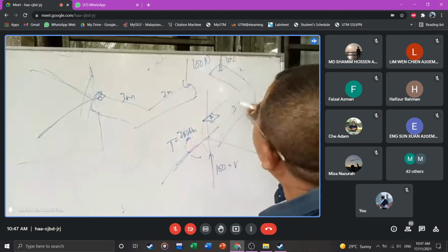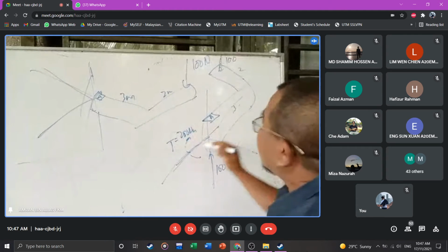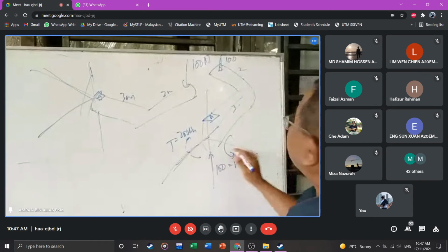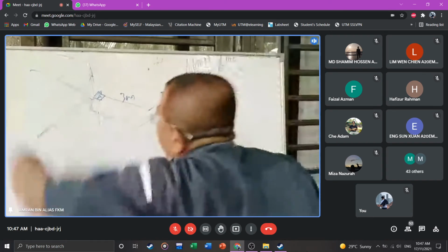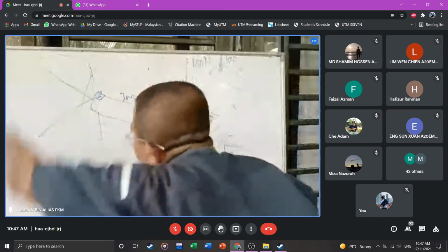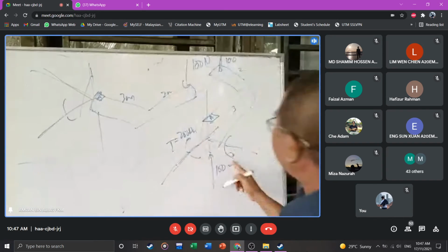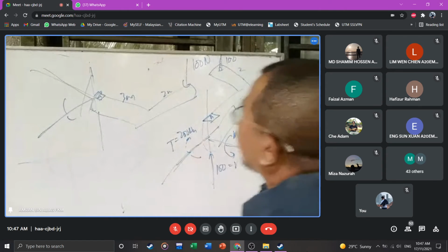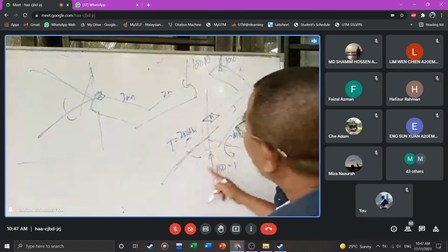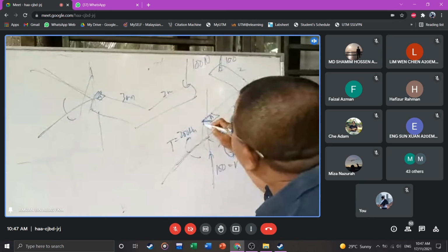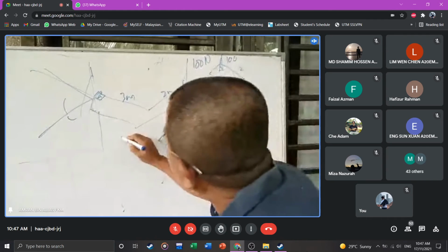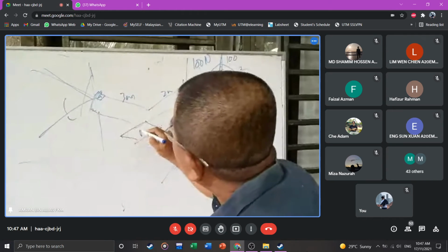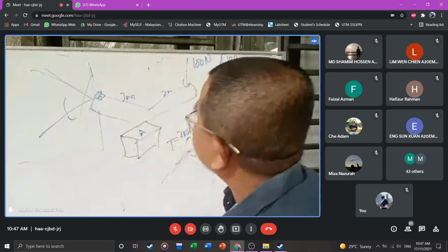And then 100 times 3 is bending on that axis, so it resists that one. The wall resists that one because bending down resists that axis. So the moment is equal to 300 Newton meter. Then you look at 1, 2, 3. How does it affect that surface there? We have done this so many times.